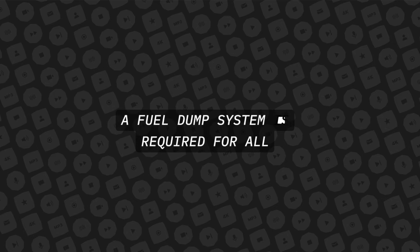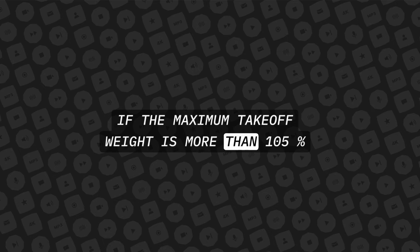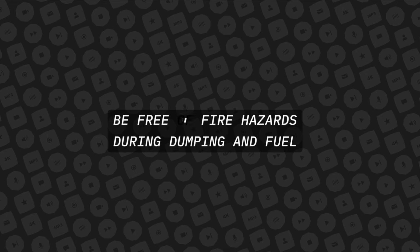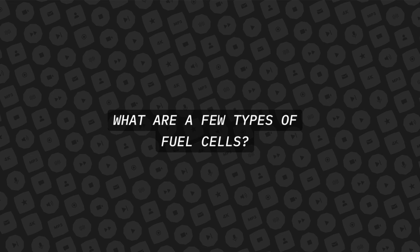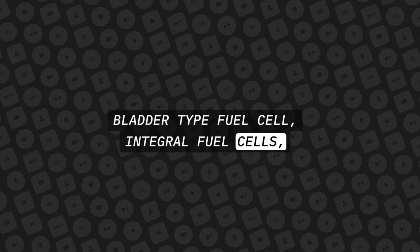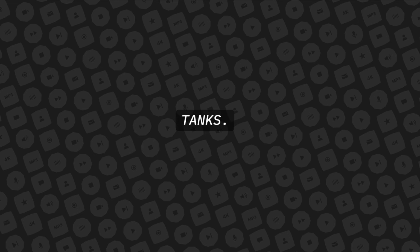A fuel dump system is required for all transport airplanes. If the maximum takeoff weight is more than 105% of the maximum landing weight, the airplane must be free of fire hazards during dumping, and fuel must be dumped free and clear of the airplane. What are a few types of fuel cells? Bladder type fuel cell, integral fuel cells, integral fuel tanks, and welded or riveted fuel tanks.